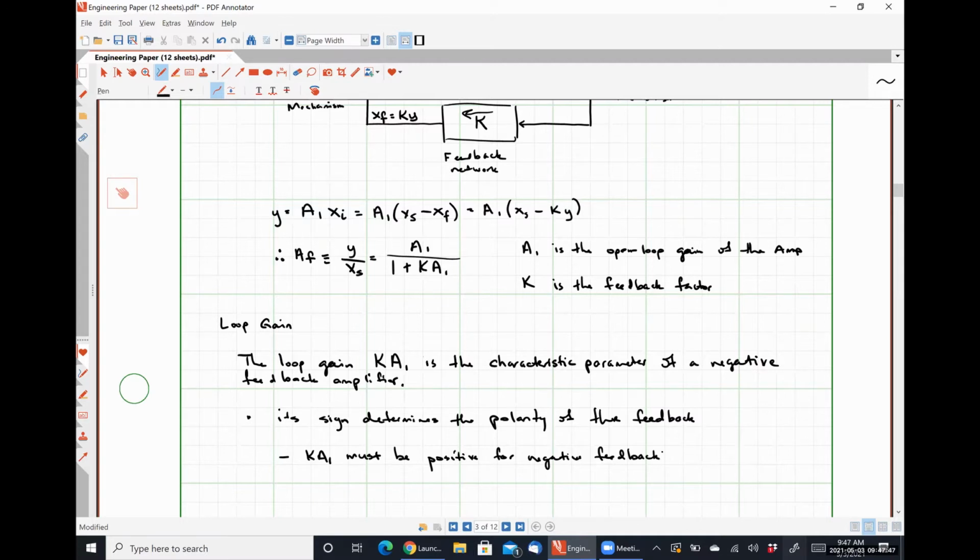which you would think would be pretty easy to achieve, and in most cases it is, but we'll see that even if we have a system where we choose a resistor network or something like that, it can be practically impossible to keep the loop gain positive at certain frequencies because of internal capacitances and things like that. We'll see that we get a 180-degree phase shift and make our system wildly unstable because we're accidentally applying positive feedback at those particular frequencies. So that's where our ability to analyze poles and things like that comes into play in looking at system stability.